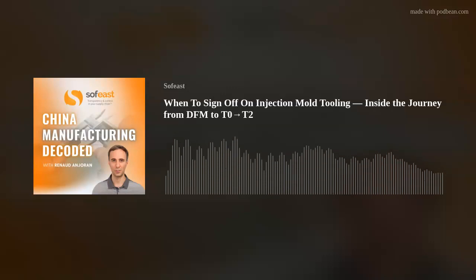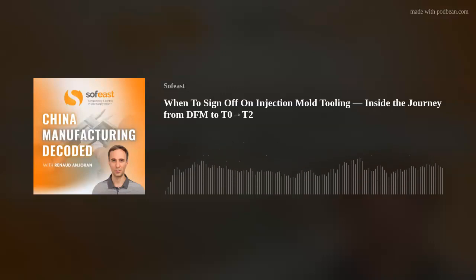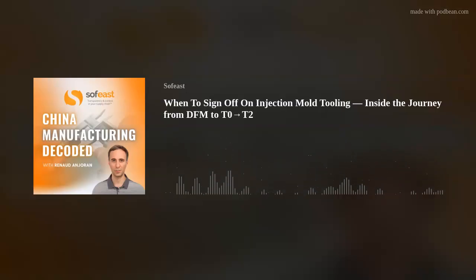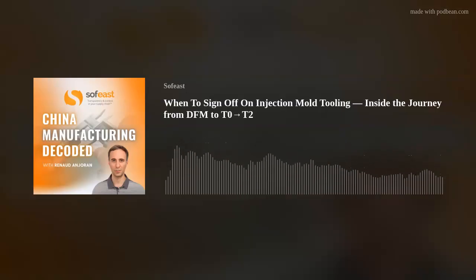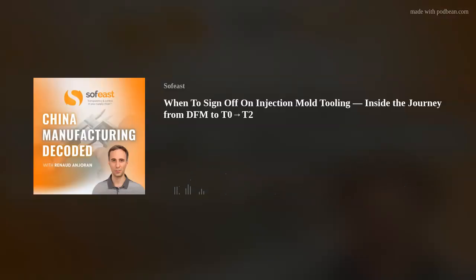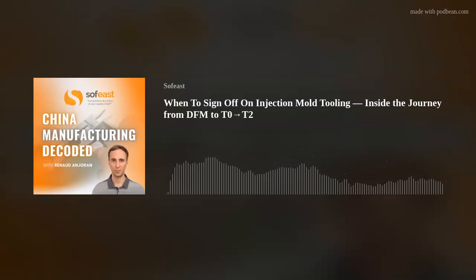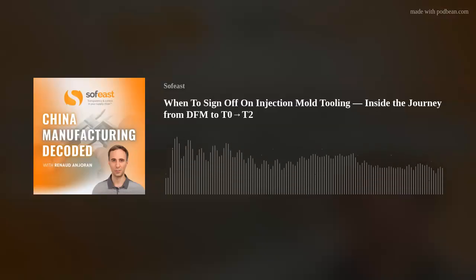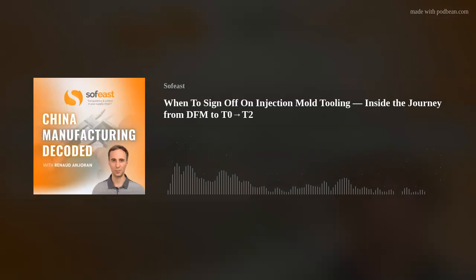And we're talking about, there's two main sections to a mold tool. There's the outside part, which is generally known as the bolster set, and the inside part, which is the core and cavity. The core and cavity is the steel parts that produce your actual plastic parts. So this is where a lot of the time and effort goes when we get into the machining and fitting, which I'll come on to in a minute.